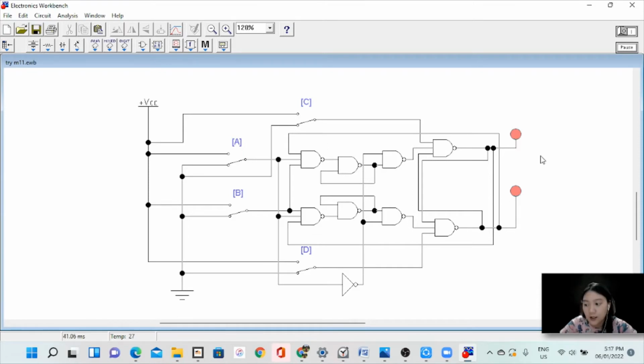And if the clock is 0 but the toggle is on high or is at number 1, it is still on hold. So it is correct. So as we can see, it is simultaneously blinking. So if C and D are connected to the VCC, the output or our probes are blinking. Thus, they toggle and they keep on toggling.